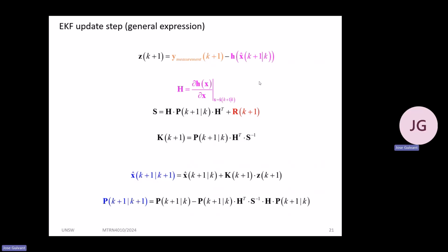So we had this prior expected value and prior covariance matrix, which also were talking about the same variable, the state vector at time k+1, but they did not use any information from the current measurement. That is why we said they are the prior, and then we apply this thing and we get the posterior. And this is the definition of the Kalman filter update, which we know from the previous lecture.